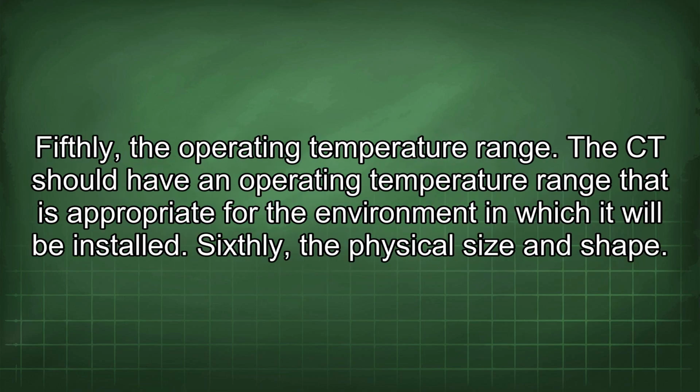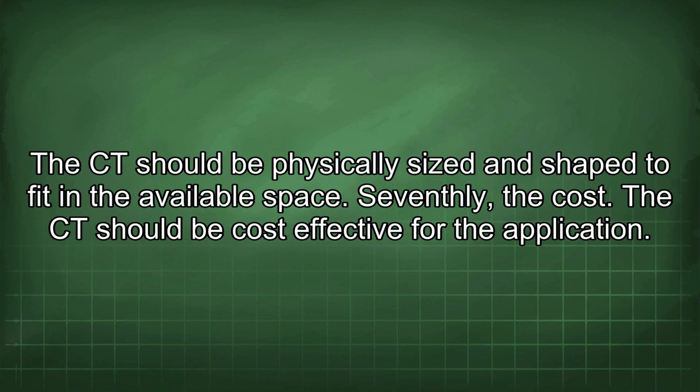Fifthly, the operating temperature range. The CT should have an operating temperature range that is appropriate for the environment in which it will be installed. Sixthly, the physical size and shape. The CT should be physically sized and shaped to fit in the available space. Seventhly, the cost. The CT should be cost-effective for the application.